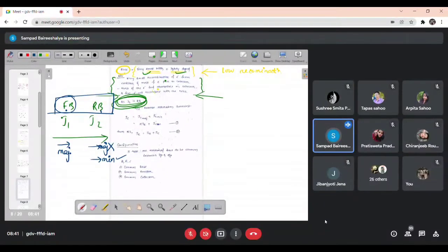मेजॉरिटी भी मूव कर रहा है उसके साथ माइनॉरिटी भी, बट दैट इज वेरी लेस अमाउंट, दोनों मूव कर रहा है, दैट्स व्हाई as a majority and minority carrier both moves, that's why I told you bipolar. Bipolar means both electron and hole. Okay, if it will be NPN type of transistor, so here this will be electron type, here this will be hole type, means electron भी move कर रहा है, hole भी move कर रहा है, as both carrier take part in conduction, that's why it's called bipolar. तो अभी समझ में आ रहा है bipolar क्यों इसको बोला जाता है?